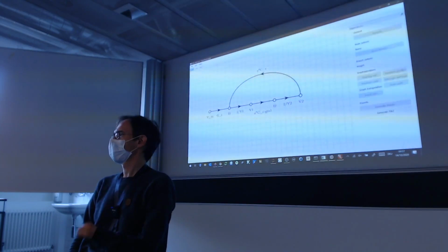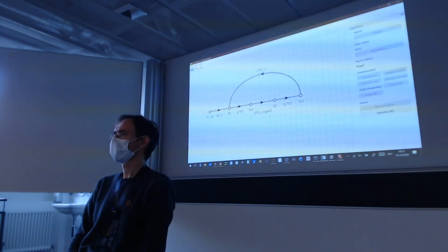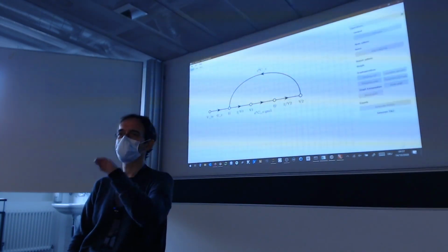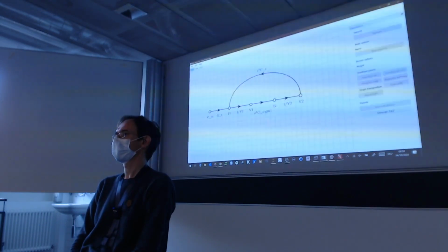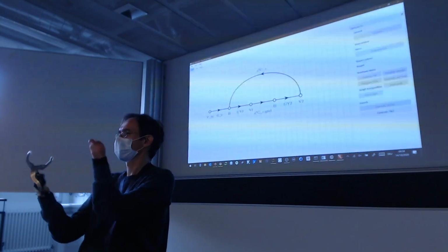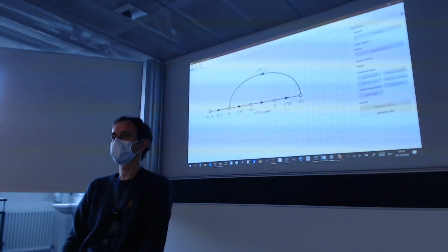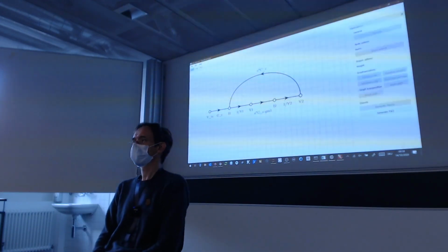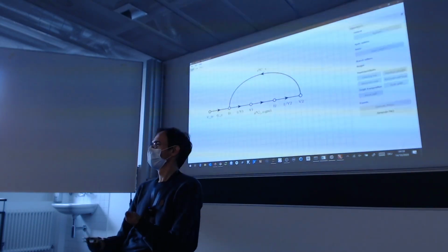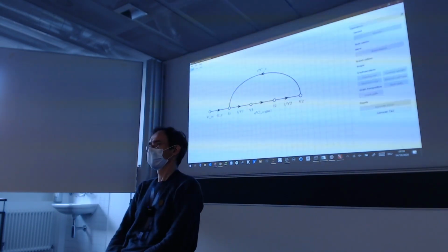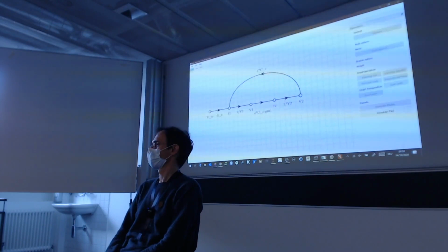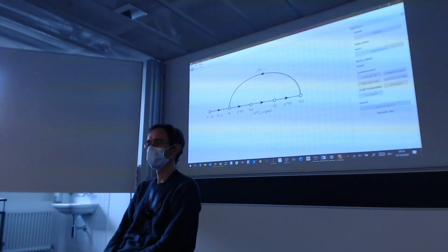And this ad hoc method of saying where the poles go is totally okay as long as you don't have feedback. So this would be where the poles are before the feedback is taken into account. But the feedback can, of course, always change it. So you have to be careful if you want to do the ad hoc guess of where the poles are lying. Of course, the analysis with the graph will always tell you the truth.